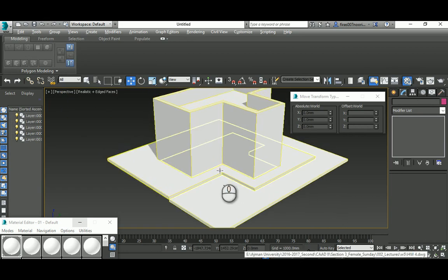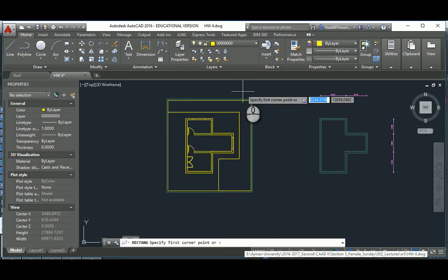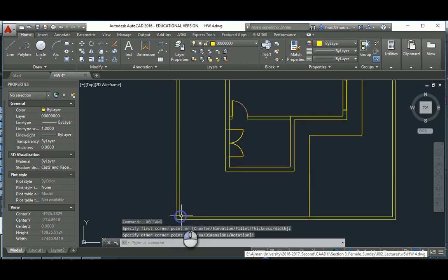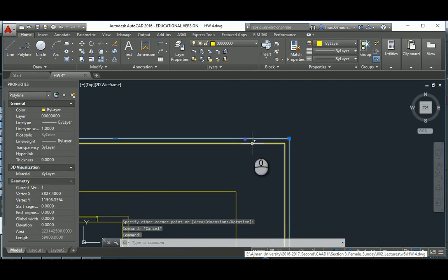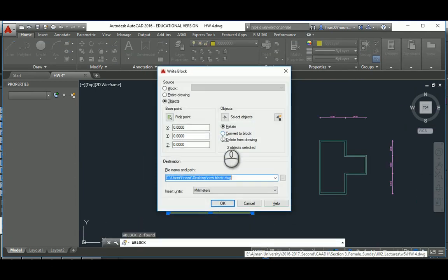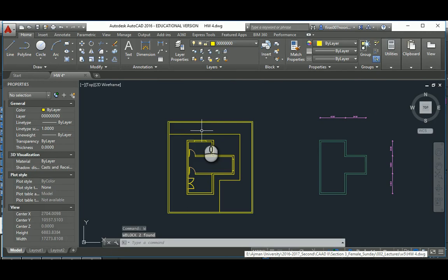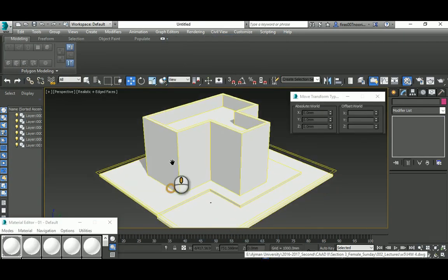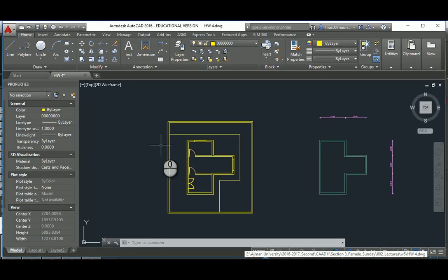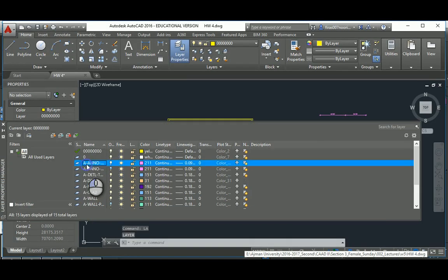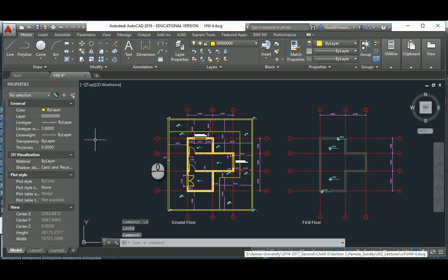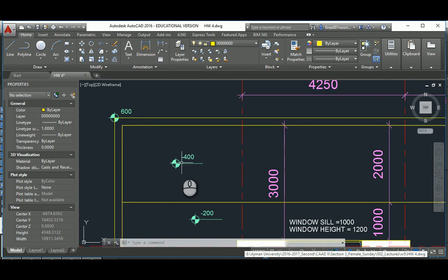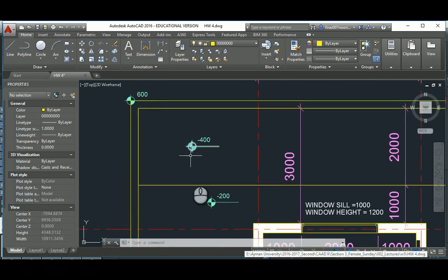And finally we go to the exterior wall. I'm going to use the rectangle command from here, and then rectangle here, and by clicking, not by crossing, I'm going to select those two, right block them, hit OK, and replace. Keep saving on the same file, and then import it. Now where to place them? If I activate all the stuff here again, it should follow the lower level, and thank God I didn't add any external level, so it should go to -400, because it is adjacent to minus 400 and minus 200.